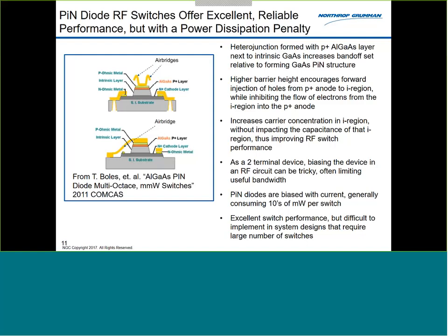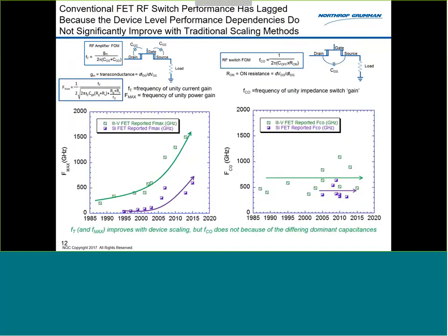But on top of that, you also have to worry about how you're going to do the design, and that's because the pin diode is a 2-terminal device, not a 3-terminal device. That really complicates your control mechanism for that pin diode, how you insert it into the circuit. Generally, that really limits the bandwidth. In general, it's just a really hard technology to access and use because of that.